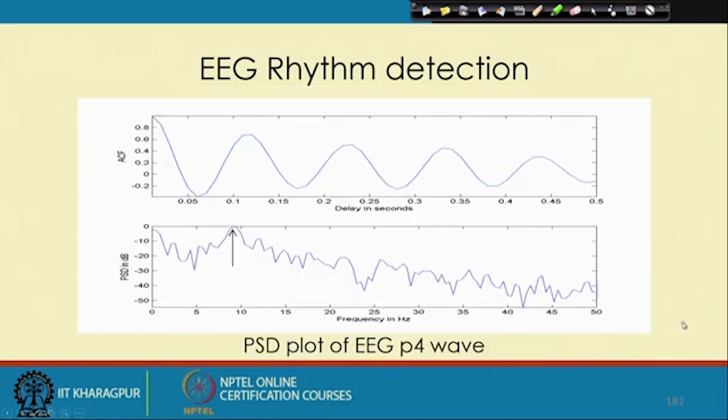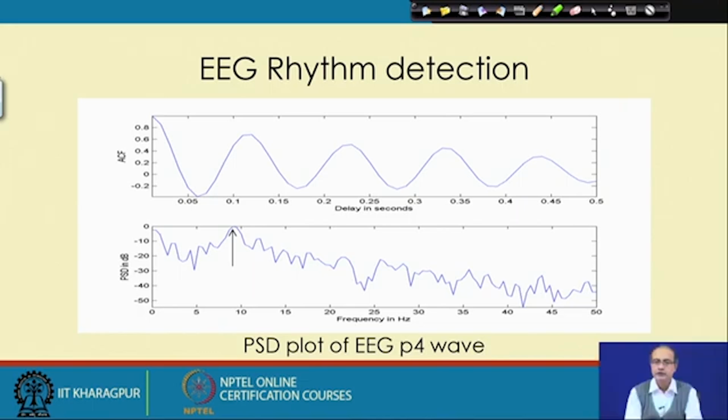Now we repeat this, but we would like to compute the PSD. We have taken the frequency plot and computed the frequency amplitude. Why are we talking about the amplitude specifically? Because while taking the Fourier transform we use e to the power j omega, so a real signal can give a complex output, and we are just interested in its strength, or amplitude.